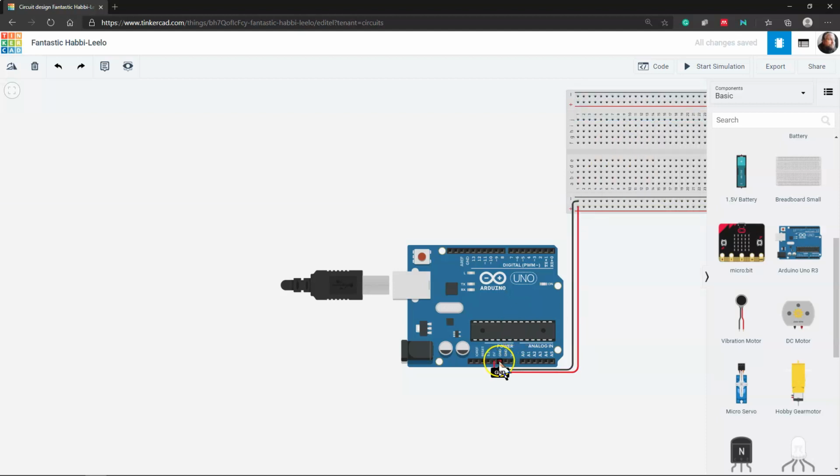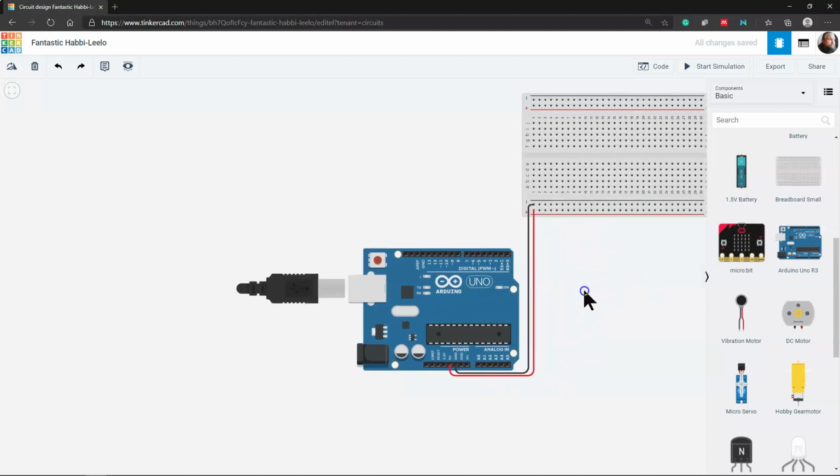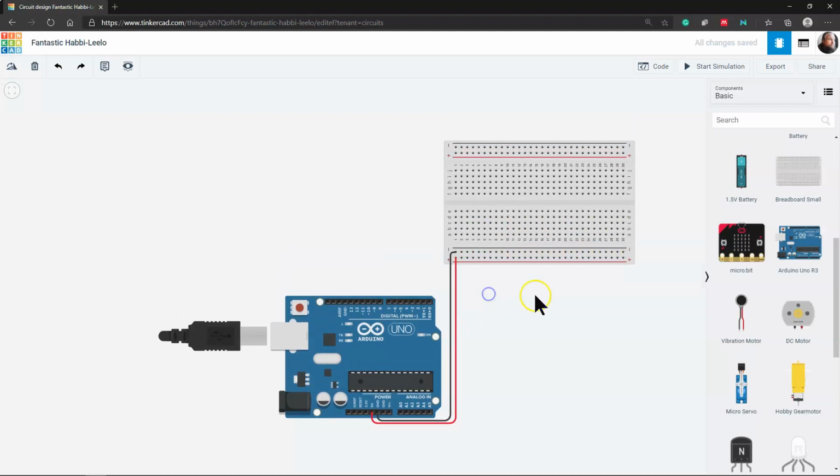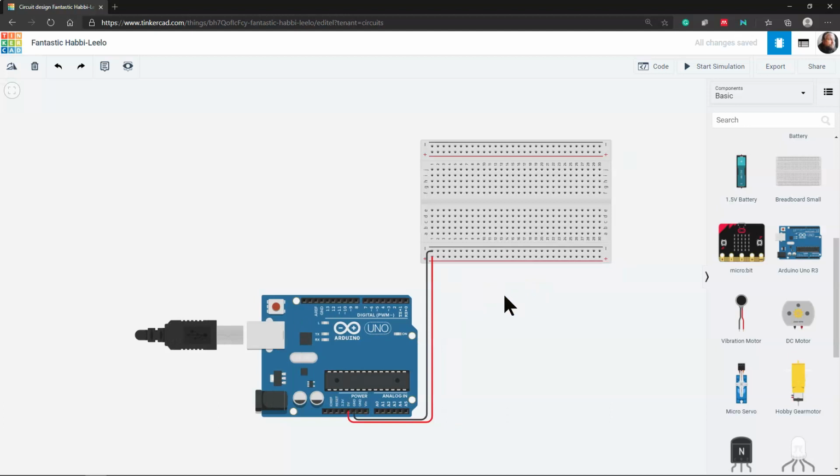So what we've done there now is that we have our ground going up and we have our power. And in this case, remember, these are not pins that we can control. They'll just be that when the Arduino gets power, 5 volts comes out here, and then the ground is along this line. So now we know we have ground all along here, and we have 5 volts all along here that we can pull along. Next, we want to pull in an LED and a resistor. And remember, the resistor's there just so that we don't have too high of amps, just being careful with the Arduino.